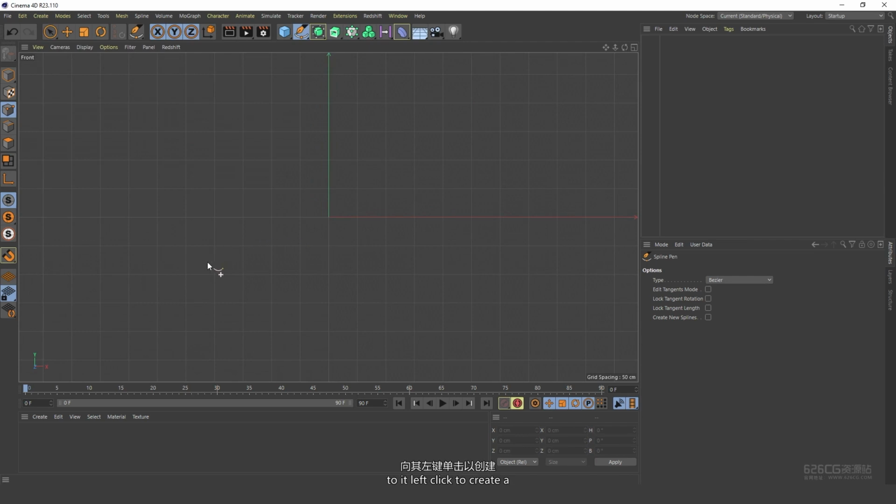After switching to it, left-click to create a spline point. If we click again in a different location, a new point is created. But this segment is linear. In order to get a point with Bezier handles, you need to hold down the left mouse button and drag. This way you can customize the shape of the spline. To disable the tool, press Escape.